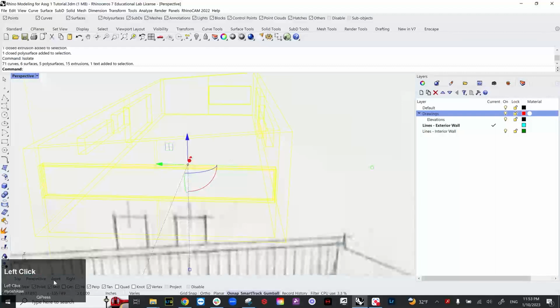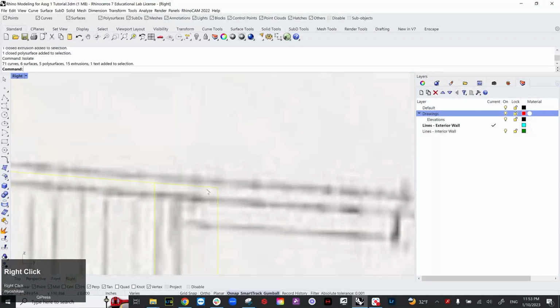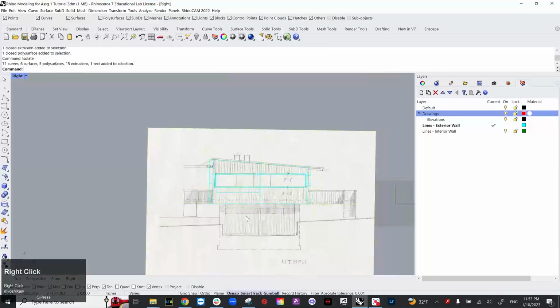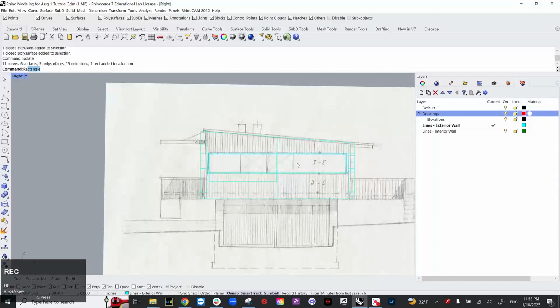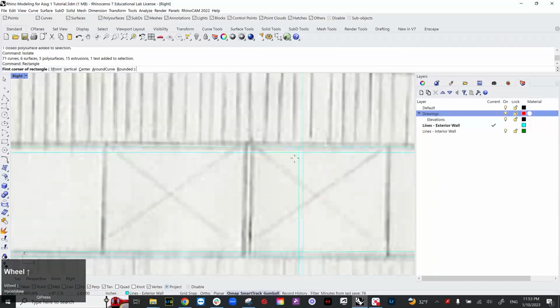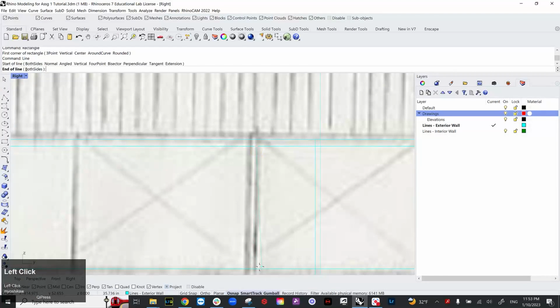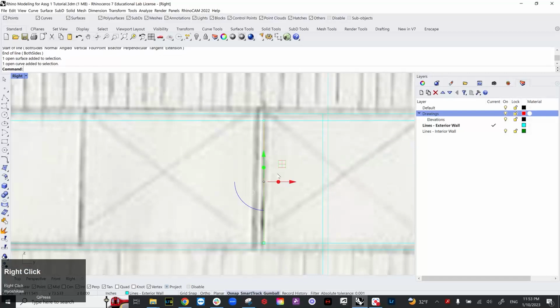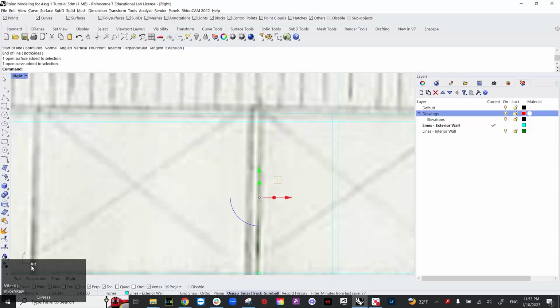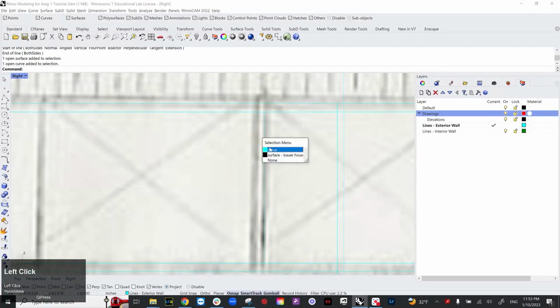Isolate, going to front. All right. And I'm going to check project and click on draw a line over here, straight line, and I'm going to make a copy of this. So I'm going to press Alt and left click this and type -2, enter, and then there's this line over here.